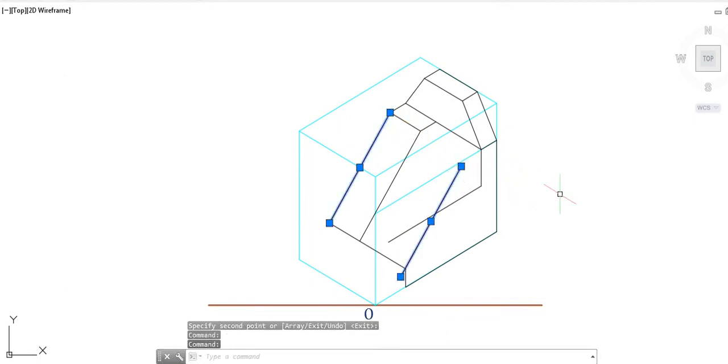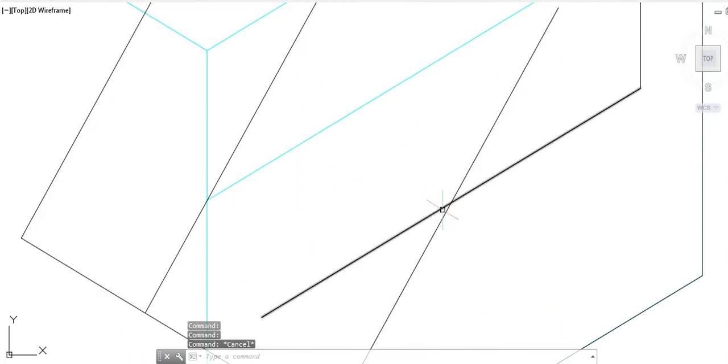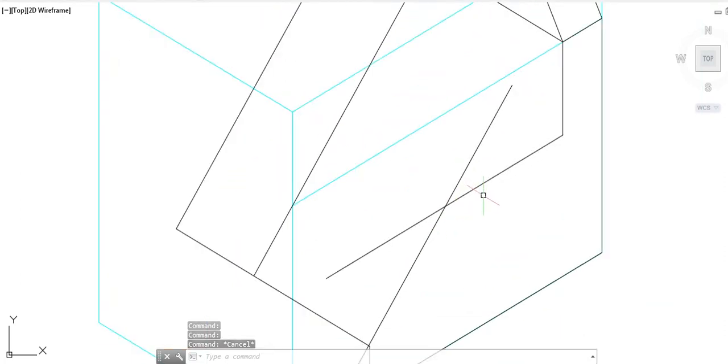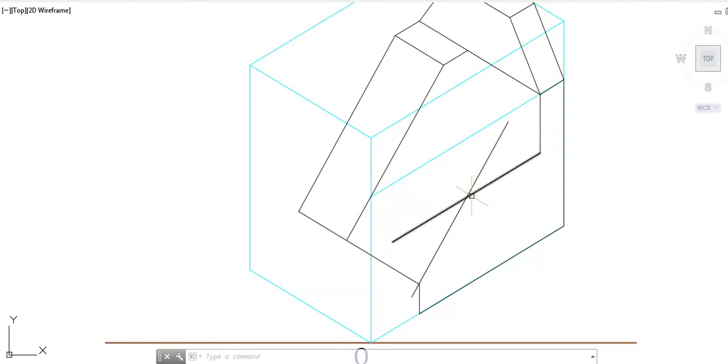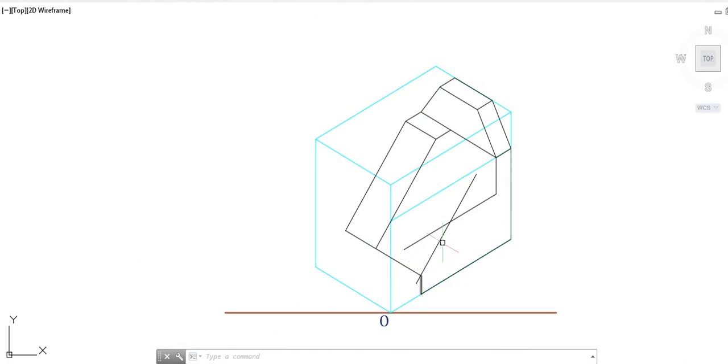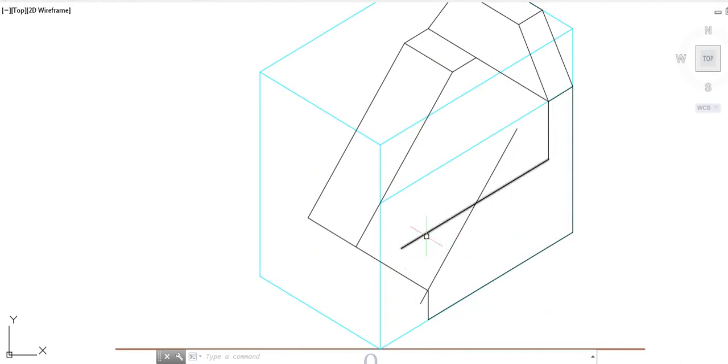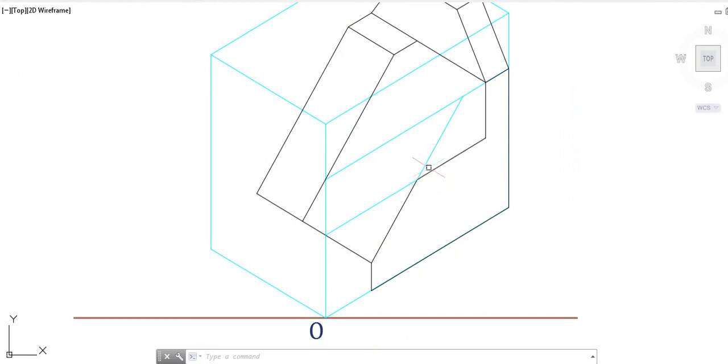Now we can see it is intersecting with this line. So what I am going to do is I am going to show only this part and this lower part. You can see it is passing through the same point, right? And from there the extra part I will keep as it is because I want to show it as a construction line. So let me quickly do it for you. So this is how I have shown the extended part as the construction line.